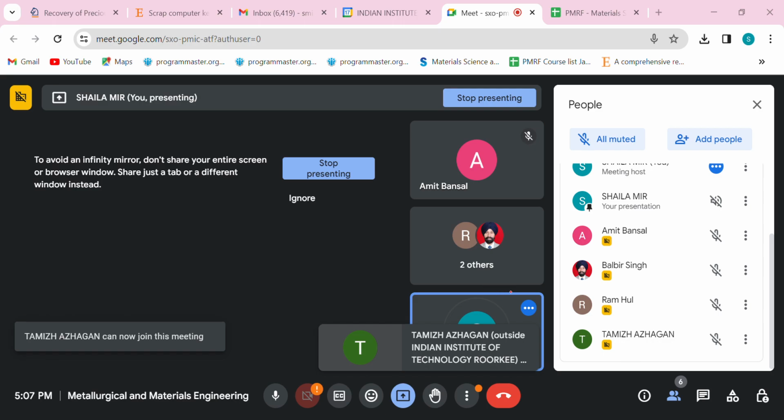So we can write 1800 multiplied by 1 by 2.5, plus your polyester, which is 55, multiplied by the volume fraction of your matrix, which is 1 minus 1 by 2.5, right? So on solving, you are getting this answer: 753 MPa.